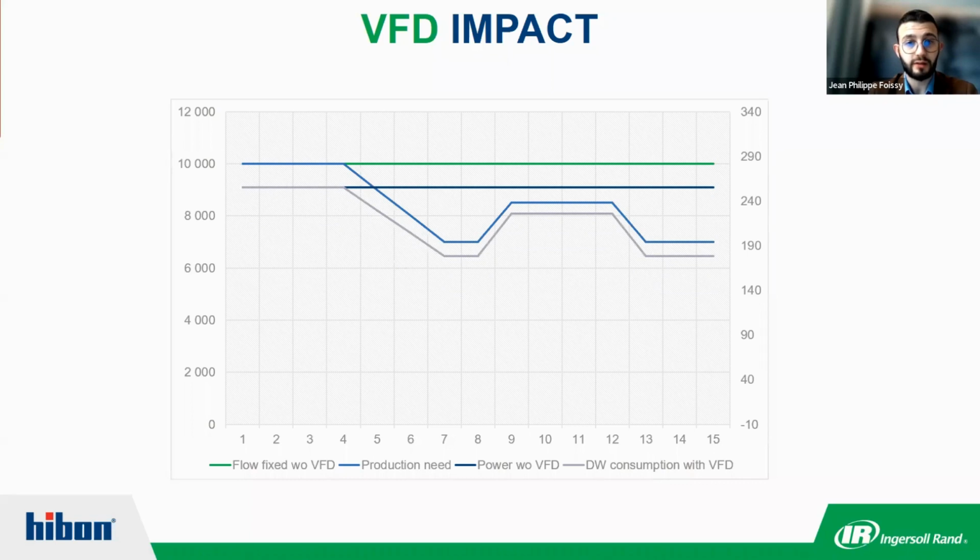And here is what we are doing with the frequency converter. So what happened? I'm focusing on the felt, on the pulp and paper machine. When you have a new felt, there is nothing stopping the air crossing the felt. So you have like a big leakage of atmospheric air. So you need a really big amount of flow, and you need to design the vacuum pumps and the vacuum system to be able to handle that. Because if you don't, you will lose some production capacity.